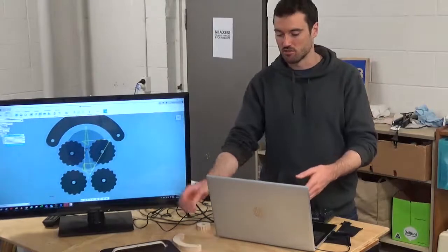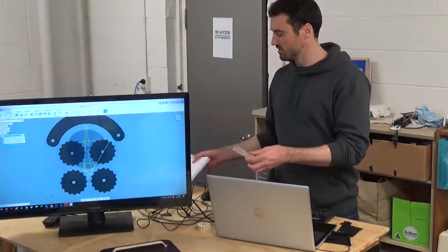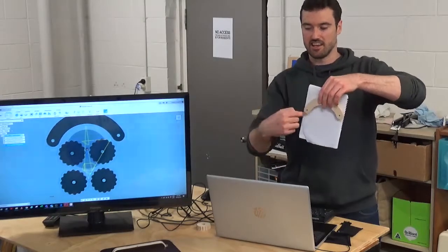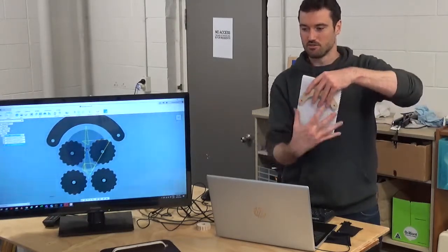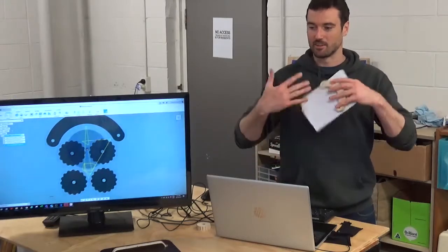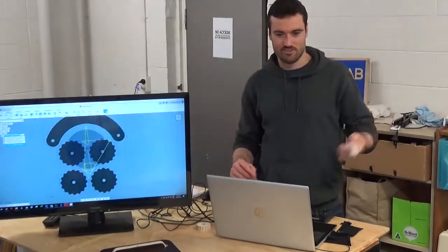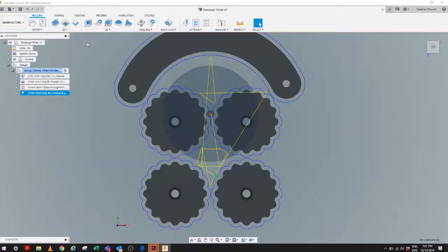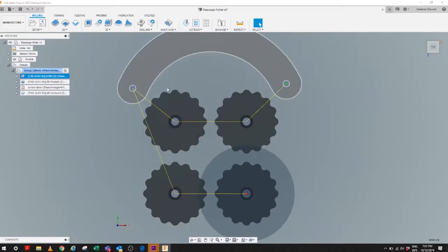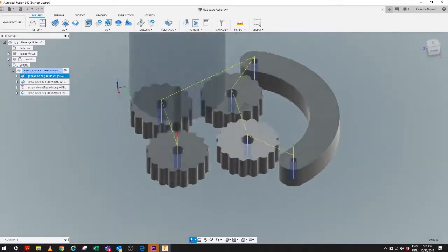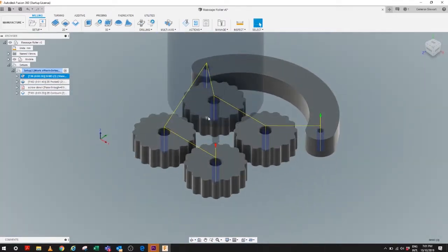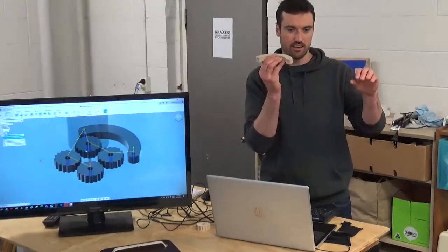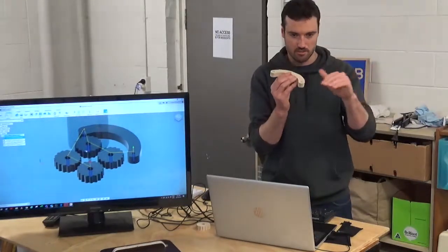But if you have a piece of stock and you put a cut across it, and it actually does cut it in half, now those two pieces of stock are independent, and now they can move. So restraint. A lot of this is about thinking about how to hold stuff down. It will also warp a little bit. So you want to make sure you have spaces to put screws in all over the place. It keeps it perfectly flat. I'd say that's very true with thick stuff like this. It usually stays pretty flat. You can put a couple of screws in, and it'll stay pretty flat.